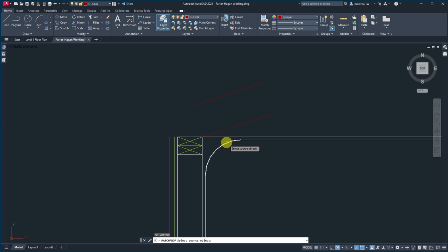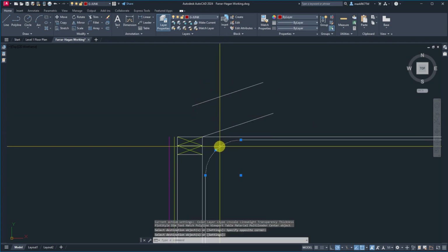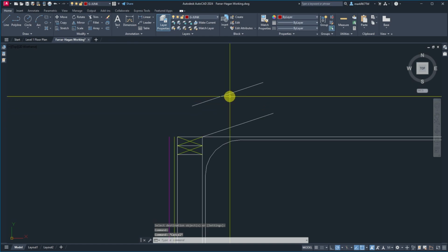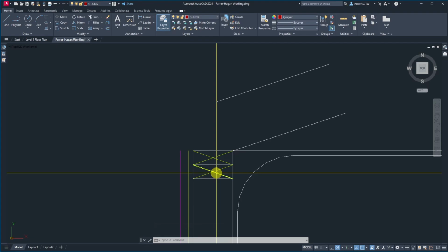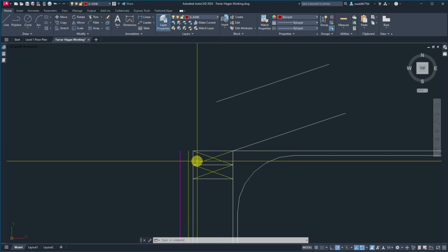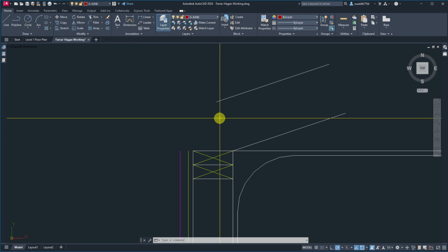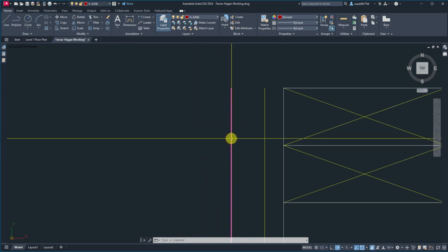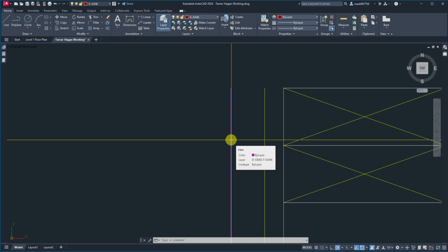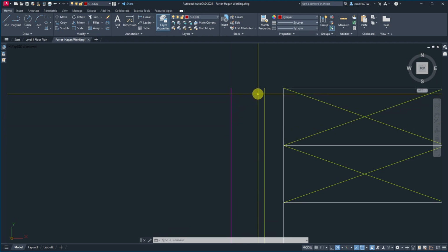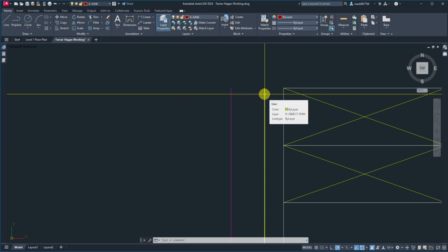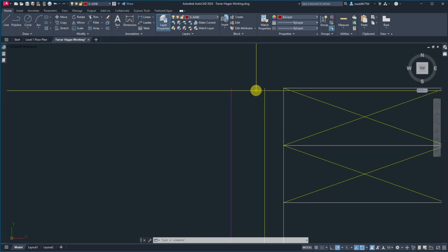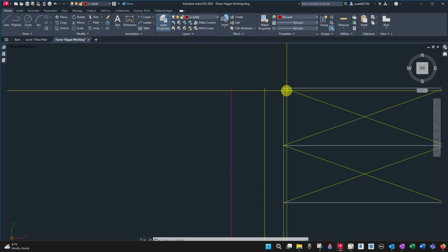So I'm going to match properties here, because this is on the D object. Okay. So just like everything, all of this is drawn on D object. These would be blocks, but they're odd sizes. They're 4 1/4, or I would have inserted blocks. Now, from this outside edge of my fascia at the top, where it comes in, out is 10 inches. So I'm going to go 9 3/4 from here, so I lose a quarter for how these lap siding come in.